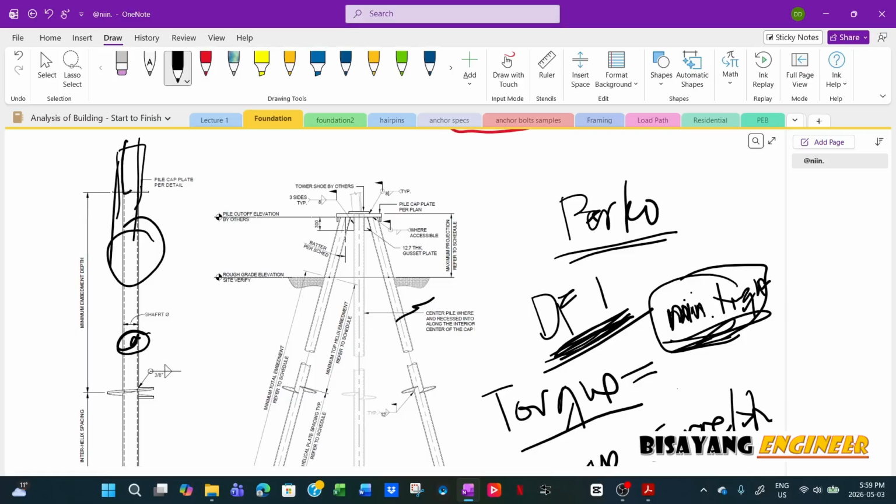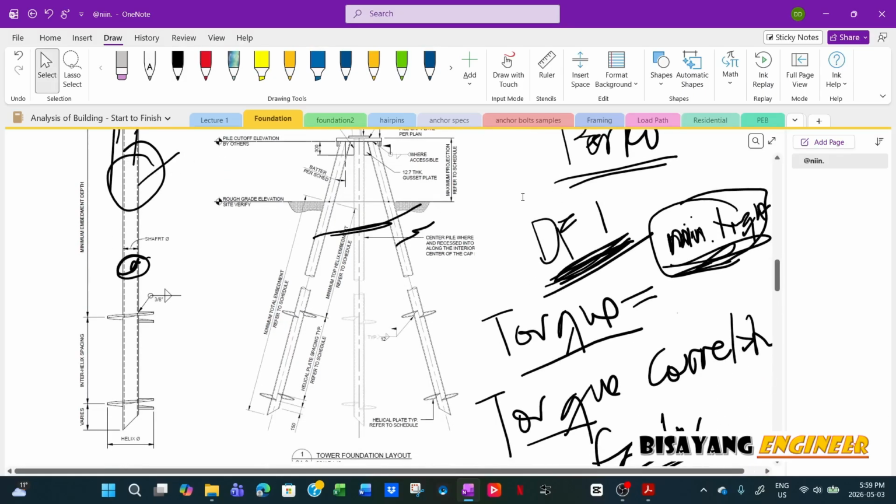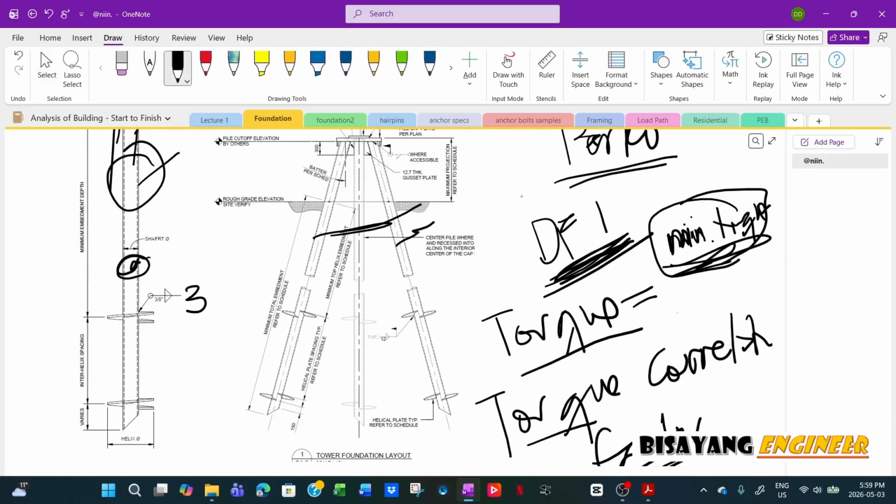It really depends. It can be used as a standalone single pile, or as a single pile in battered configuration. You still have to meet the minimum requirements, the same as any cast in place pile, where you have to space the piles at least three times the diameter. This one is also three times the helix diameter.